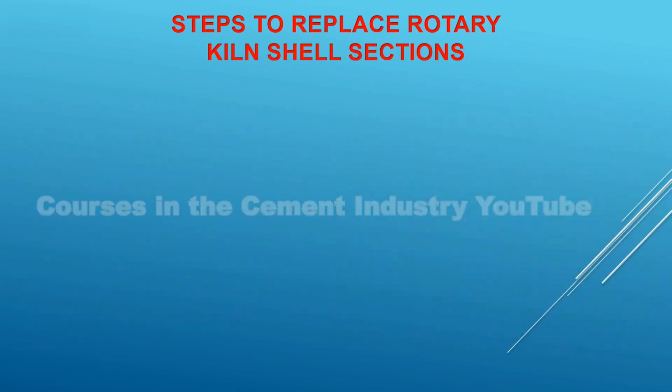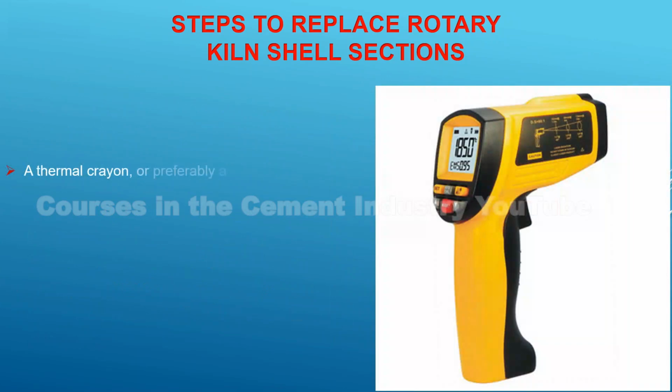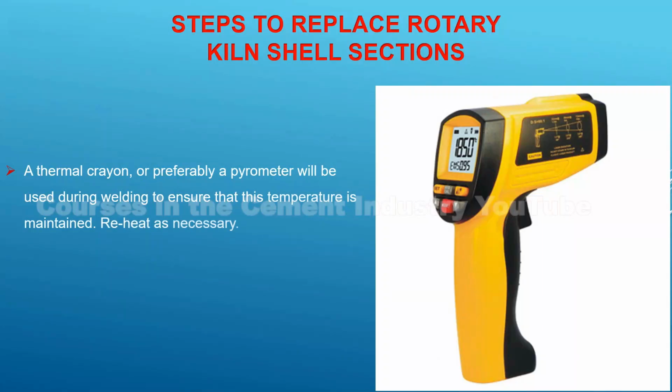Step 18. A thermal crayon, or preferably a pyrometer, will be used during welding, to ensure that this temperature is maintained. Reheat as necessary.